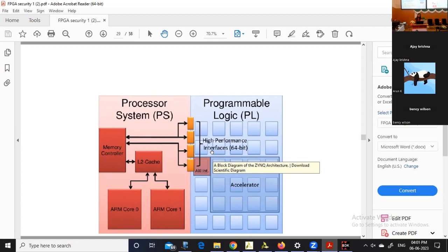If the attacker doesn't know the key bits, he will not know the logic of the circuit because we have kept so many gates. He doesn't know the logic of the gate, and he doesn't know where to keep the Trojan. He doesn't know whether the trigger will activate the Trojan or not, because the trigger circuit will be there, and in between our additional gate will be there. Key is there. So his trigger may or may not work. Okay. So almost all hardware level attacks can be avoided by logic locking.